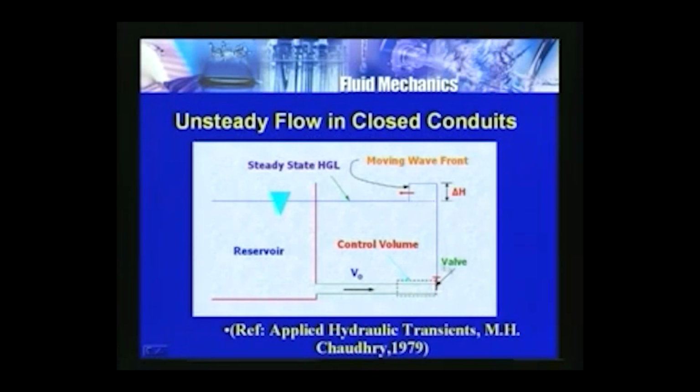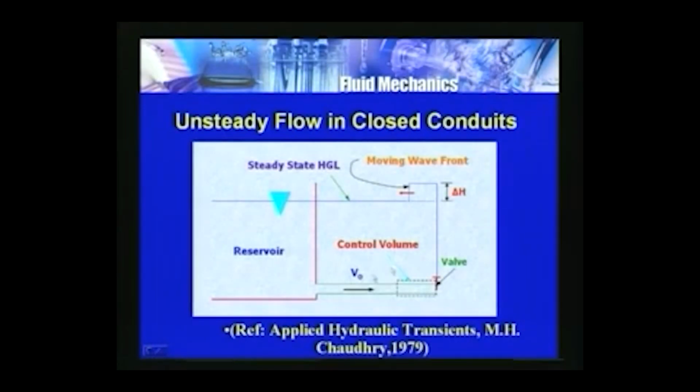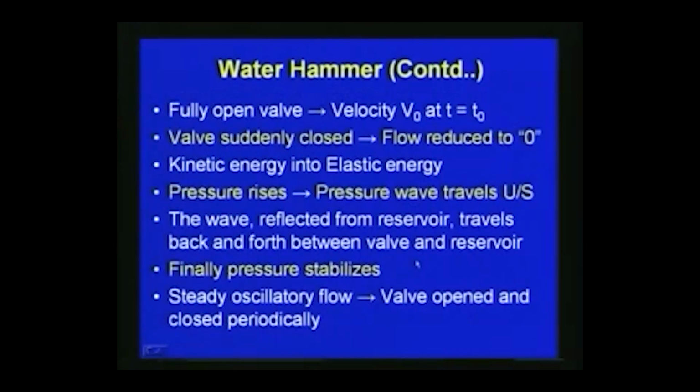Due to the sudden closure the pressure rises and a pressure wave travels to the upstream side, and then the wave is reflected from the reservoir and travels back and forth between the valve and reservoir. This happens for some time until the intensity of the pressure reduces, the water hammer effects reduce, and finally the pressure stabilizes.